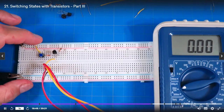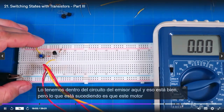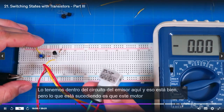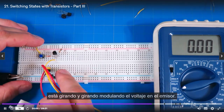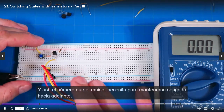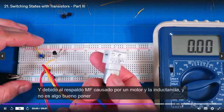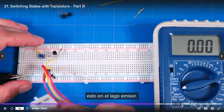Now, we have the meter inside of the emitter circuit here. And that's okay, but what's happening is as this motor is turning around and turning over, it's modulating the voltage on the emitter, right? And remember, the emitter needs to stay forward biased. Because of the back EMF caused by a motor and the inductance in it, it's not a good thing to put this in the emitter leg.